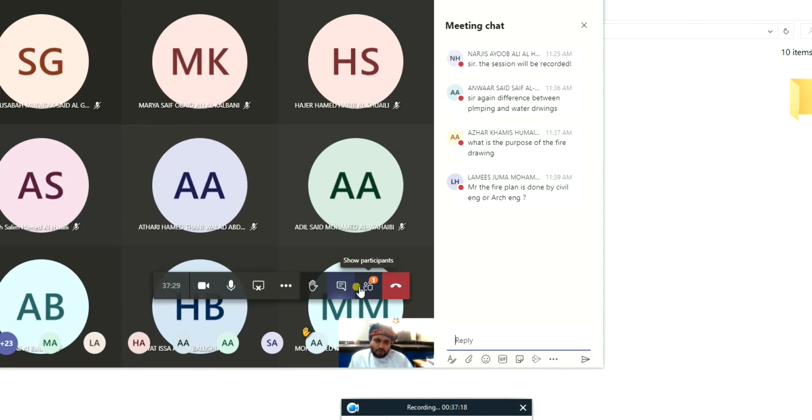The number of exits should be enough. In the same way, when we talk about the number of staircases or number of lifts in buildings, they are not only for the purpose of adding a staircase. Like if you remember in your civil building, you have two stairs. It's not only for the purpose of adding stairs for the sake of paying more money. No, because of the huge number of students in that particular building, you cannot have them all go out from one particular exit. Hope that's clear for you as well.